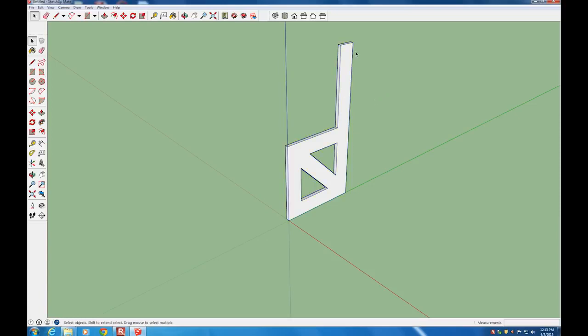It looks just like the normal model, but to edit it, you have to double click. And then you get this little gray box around the part, and now you can work with it just like it's a normal SketchUp part, except that it's going to behave a lot nicer and not stick to your other geometry. All right, so once one side of this is made a component, we're going to copy it so we have two pieces of the chair.